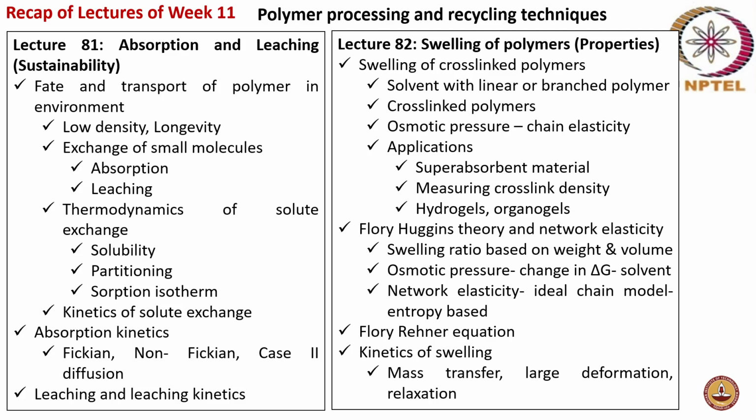Next, lecture 82 was on swelling of polymers, which is a property based lecture. So, swelling of cross linked systems. What happens if a solvent comes in contact with a linear or branched polymer? It actually gets plasticized, and then solubilization starts taking place, and then you end up in a polymer solution. Whereas in case of cross-linked polymers, there is no dissolution of the polymer, but there is a swelling that takes place upon solvent uptake, because of the cross-linking present in the polymers.